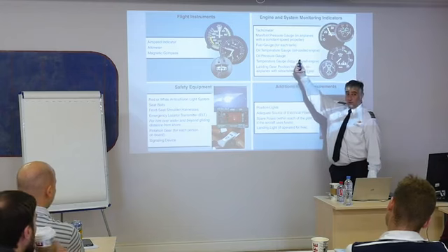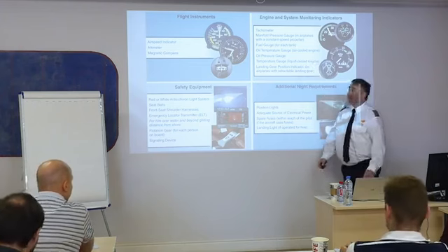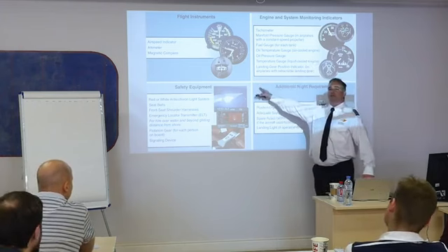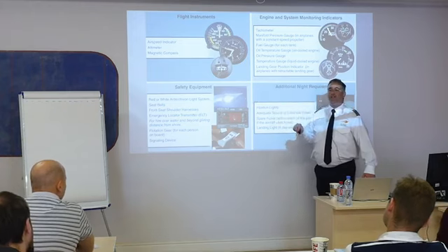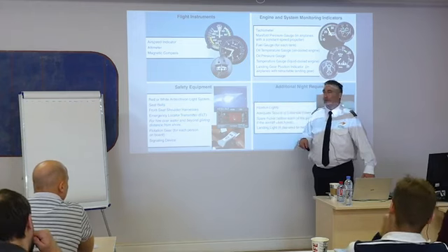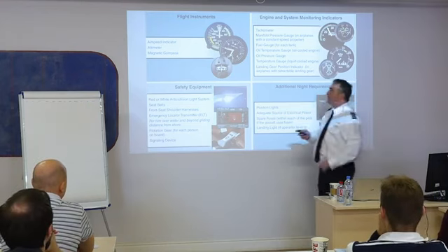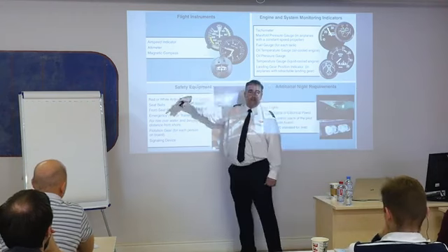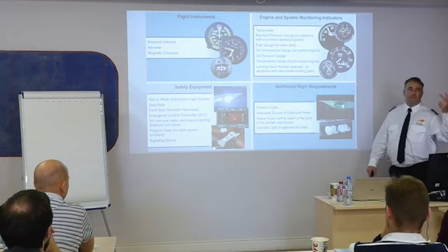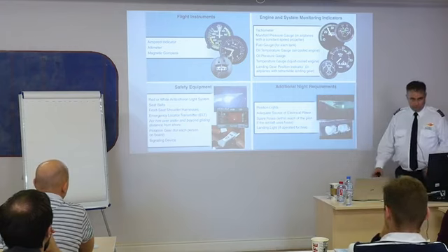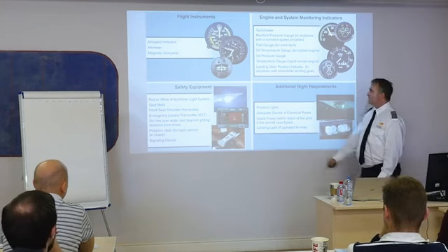Whoever's soloing. You're the only one in there. Somebody needs to command it. Hopefully it's you, right? It better be. You have to make this decision of, do I have all the equipment that I need to make this flight? Okay? So some of the stuff you need, easy stuff for flight instruments, very, very little. I need an airspeed indicator, an altimeter, and a magnetic compass. If any of that stuff is broken, you cannot fly. Okay? No matter what else you have that's working, you cannot fly.